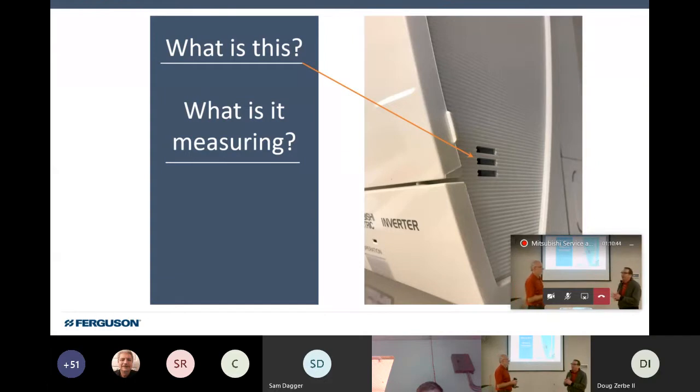And you did bring up something, Jim, and I'll just say this real quickly. That sensor does have an offset built into it. So when a consumer takes a remote and points it at that head and says, I want it to be 70 degrees, in reality, that indoor head is actually working at about, let's just say, 73 point something degrees, because it's actually a Celsius conversion. Sure, it's metric. Right. But it's figuring that extra heat up there, and it's going to cool down. So this is another reason.